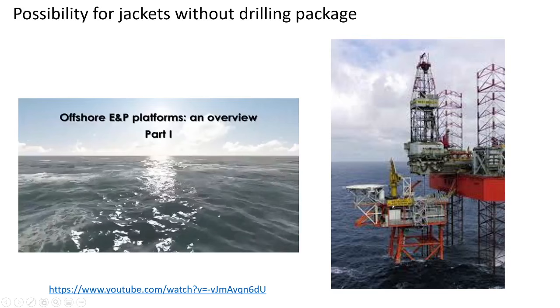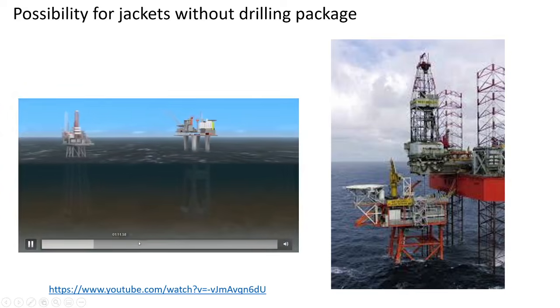Okay, it's also possible, because the drilling package is expensive, that, like in this case, you have a jacket and you drill the wells from a jackup. Okay, you see the jackup sticks out the tower, then drills the wells, and then can also be used to do intervention. So in this case, the jacket doesn't have to have a drilling package, which saves on cost. But at the same time, in the future, if I have to do some operation in the well, I have to call this guy to ask for the service.